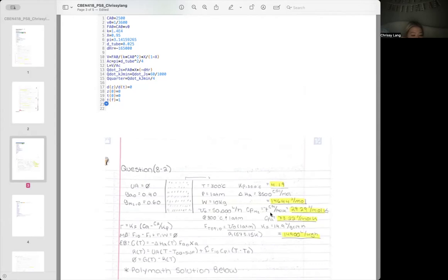After that, I set up the energy balance, which included the heat of reaction term, the temperature-dependent heat capacities, and the possible contribution from the heat transfer term. Rearranging this gave an explicit expression for dT/dV that couples with the mole balance, so the temperature and conversion evolve together throughout the reactor's volume.